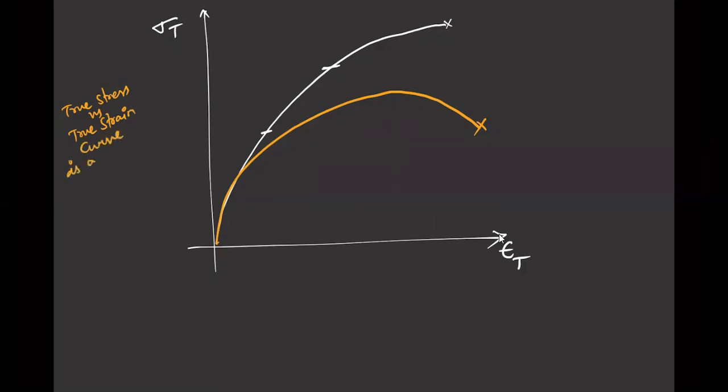That means my true stress versus true strain curve is always above and to the left. Okay, so you can see it's to the left of the engineering curve. This is an important part you have to remember, of the engineering curve.